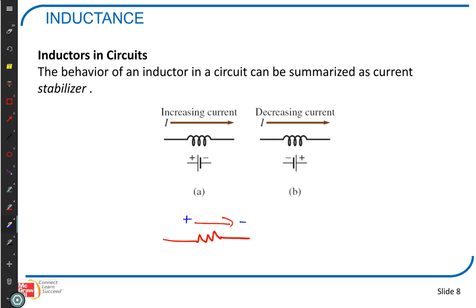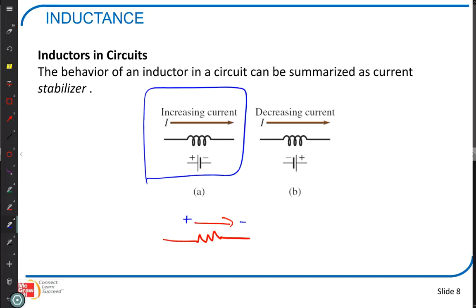With the inductor, if the current's increasing, then it's the same. If the current is decreasing, it's reversed. Well, when we start doing circuits, we're going to use this because we assume a positive change. If it's a negative change, that's going to put a negative sign in our work, and it's going to change the direction for us. So we basically follow the same sign convention for drawing things. But remember, that's the direction of the voltage only when the current is increasing. When the current is decreasing, it flips to the other direction.